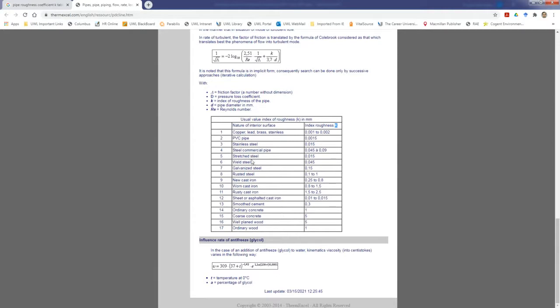So it could be one indication that the plastic pipes or other pipes do not change. The pipe roughness coefficient of those other pipes are not changed over time. That might be one reason for that, but I leave it to you to go and investigate later, because it's a controversial topic. Sometimes they might say no, it could be changed, but in some cases they might say okay, no, it's not going to change. So I've seen all these kinds of aspects as well. Okay, is that now clear?